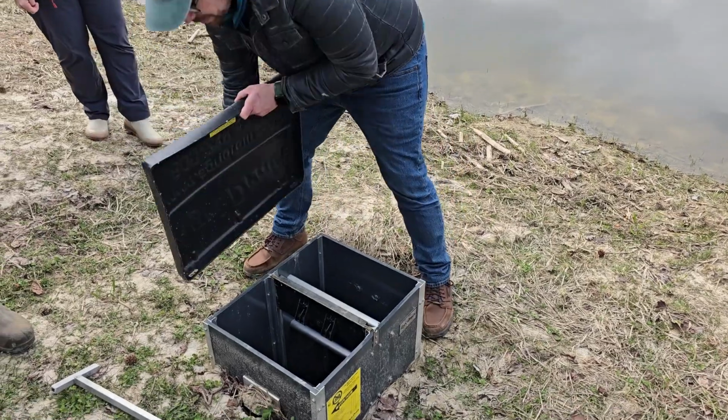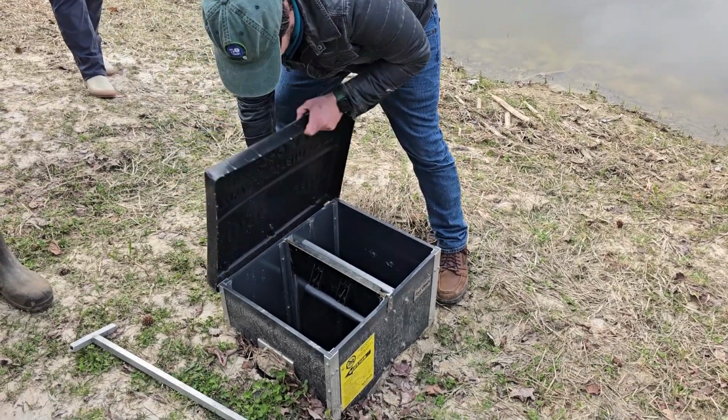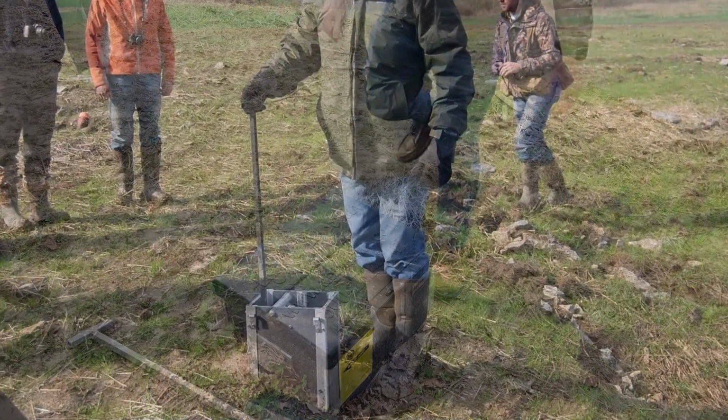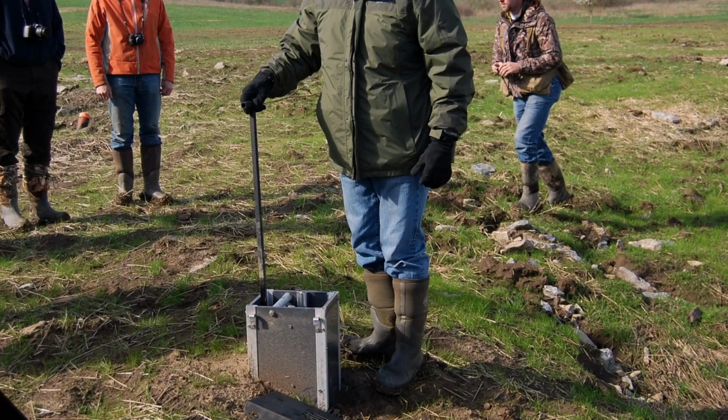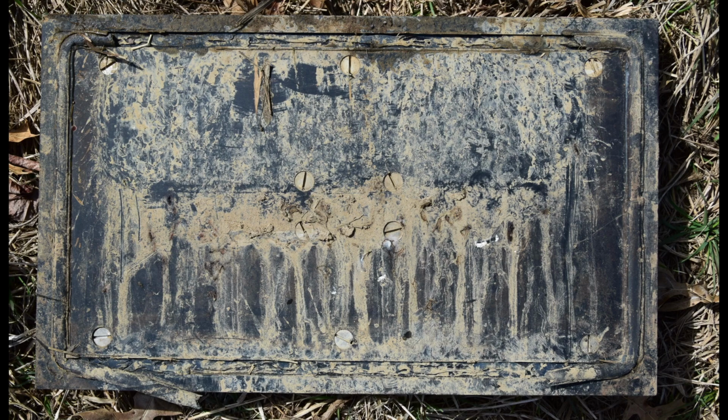The cover can be removed from the inline water control structure so the plates inside can be added or removed. A specialized tool is used to remove or to add plates for adjusting the water levels. The gaskets and the plates are prone to tearing, breaking, and compressing. This can cause the water control structure to leak and the wetland to drain.